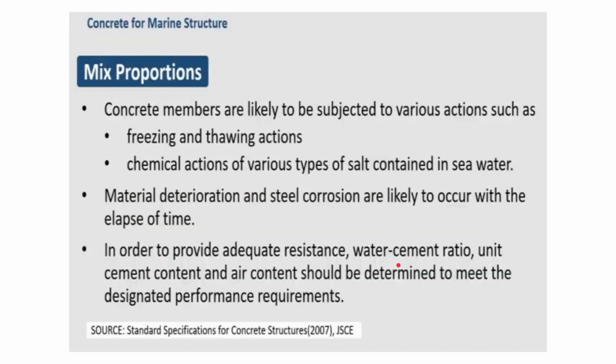Concrete members are likely to be subjected to various actions. They are subjected to freezing thawing actions, and in sea areas, chemical actions of various types of salt, basically chloride contained in seawater. Material deterioration and steel corrosion are likely to occur with the elapse of time, and in order to provide adequate resistance, water cement ratio, unit cement content and air content should be determined to meet the designated performance requirements. So all of these criteria are required to be satisfied.